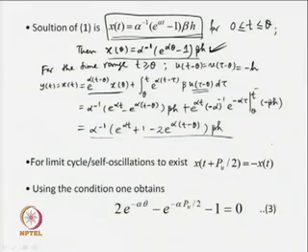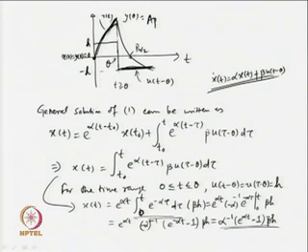After ascertaining that, we will go to the analysis of the half period of the sustained oscillatory output, where we know that the output becomes 0 at time t equal to Pu by 2. So, that can be given in the form of y(Pu by 2) is equal to y(0). Actually, since we get sustained oscillatory output, y(Pu by 2) has to be equal to minus y(0).